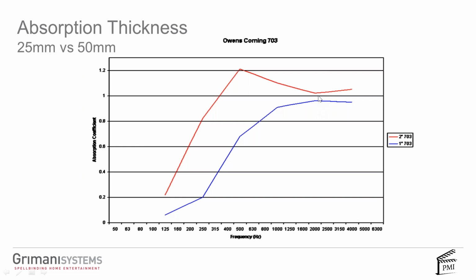So the absorber is not only absorbing in the front. If you had a 2x4 absorber, if it's a 1-inch thick one, the 1-inch band will absorb a little bit. If it's a 2-inch thick one, the 2-inch side will absorb somewhat. A 4-inch thick one will have an even higher absorption coefficient. So it absorbs more than an open window, which is impossible. It's just an idiosyncrasy of the measurement, but it does tell you something about how much more efficient a thicker panel is.